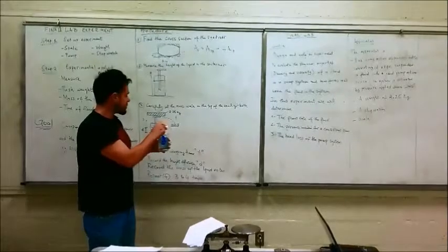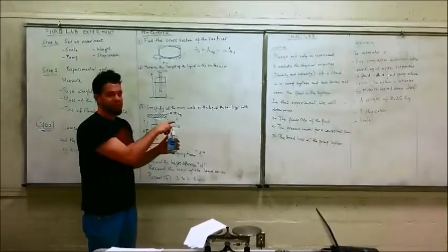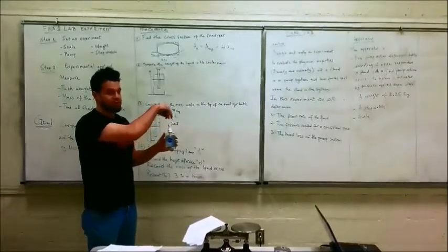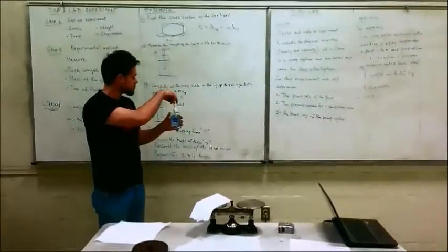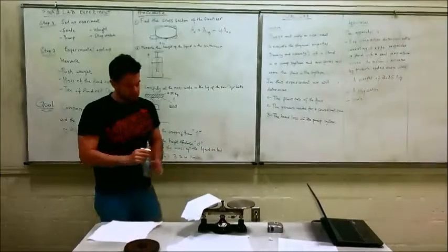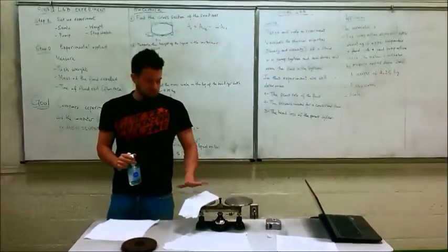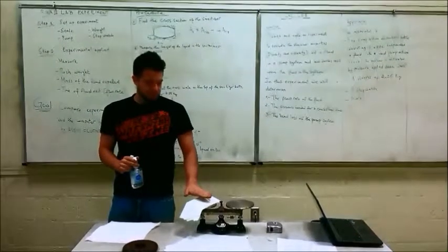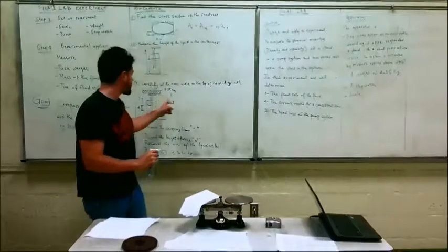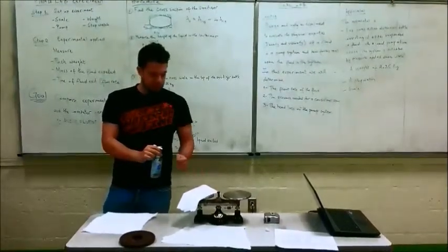Now, when it is pumped out, we will apply a mass of 2.5 kilograms on top. This is a known force applied to the vertical direction of pumping. It will expel an amount of fluid. This will be weighed on this scale over here. We will take this weight, we already zeroed it out to factor in the paper towel, which we will consider as a retaining containment as seen over here. We will measure the weight of the fluid expelled.